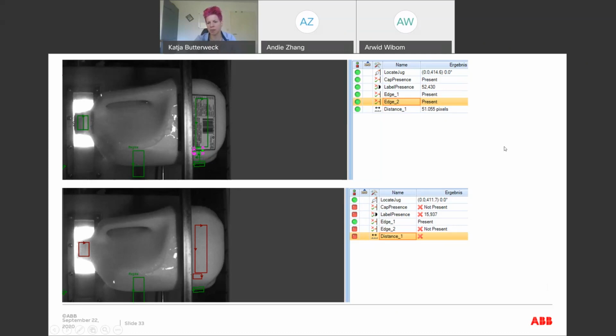So really this inspection task can very often be included in existing tasks. So if you have a robot, you have the robot doing the pick and place, but you want to add, for example, some more value, then just add a vision task, add an inspection task, because then you can really make sure that your product, maybe you need to prove that the label is already there. Maybe you need to prove that the cap is correct. The robot can take this task as well very easily.